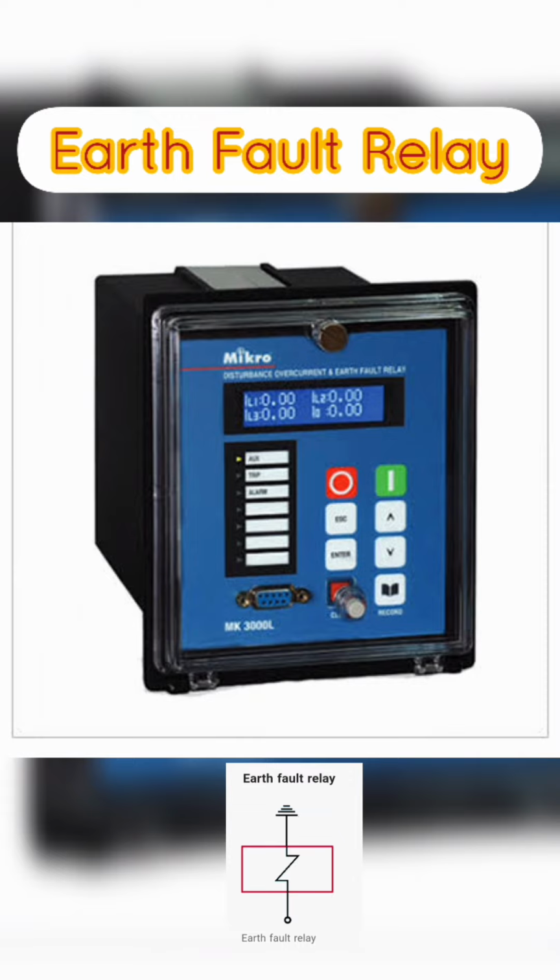The earth fault relay can be connected in various configurations, such as in the neutral of a transformer, between the neutral and ground of a system, or in the ground return path of a system. The relay can also be designed to operate on different current levels and time delays, depending on the characteristics of the system and the type of equipment being protected.